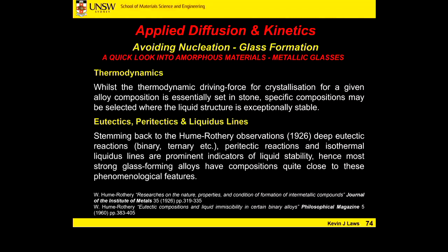And sometimes, in certain systems, it can be much lower than those two melting points. That tells us that at this very particular composition, from the bottom up, the crystallization driving force of X and Y competing with the liquid is relatively low. And from the top down, the structure of the liquid at that composition is very, very strong or low energy.